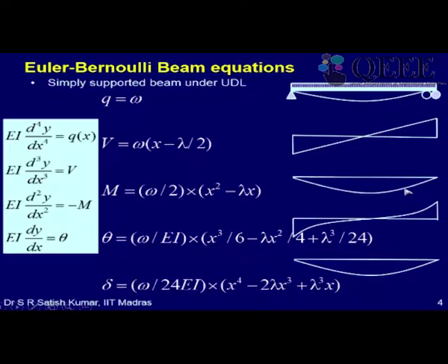And then you proceed ahead. Again the slope slowly goes on increasing, and then your bending moment becomes 0, but the diagram is steeply sloping upwards, which is the slope given by the shear force diagram. So that is what we need to understand, and the bending moment basically tells you how the beam is going to bend. So if the bending moment is high, it will bend in a very sharp curvature, that is, a very small radius of curvature. If the bending moment is low, it will be almost straight. So that is what we have to understand.